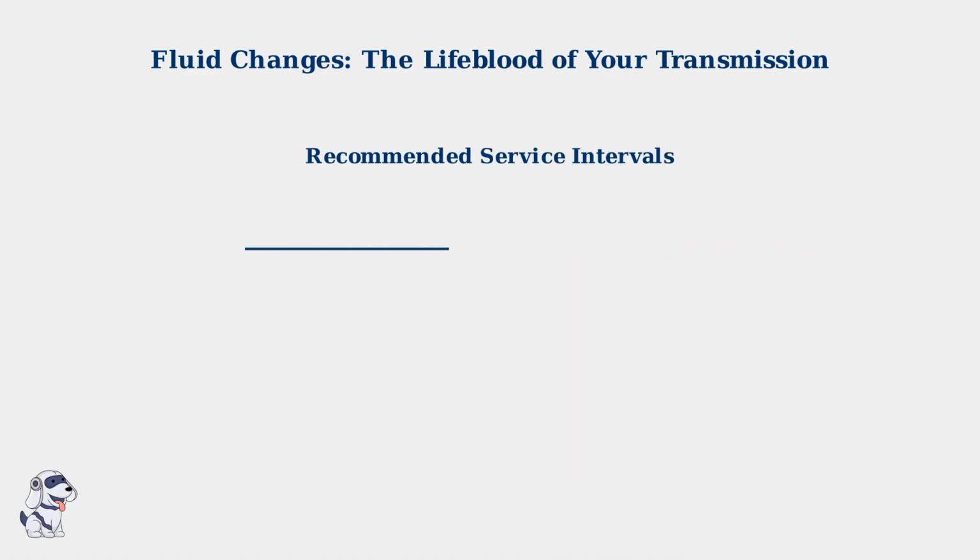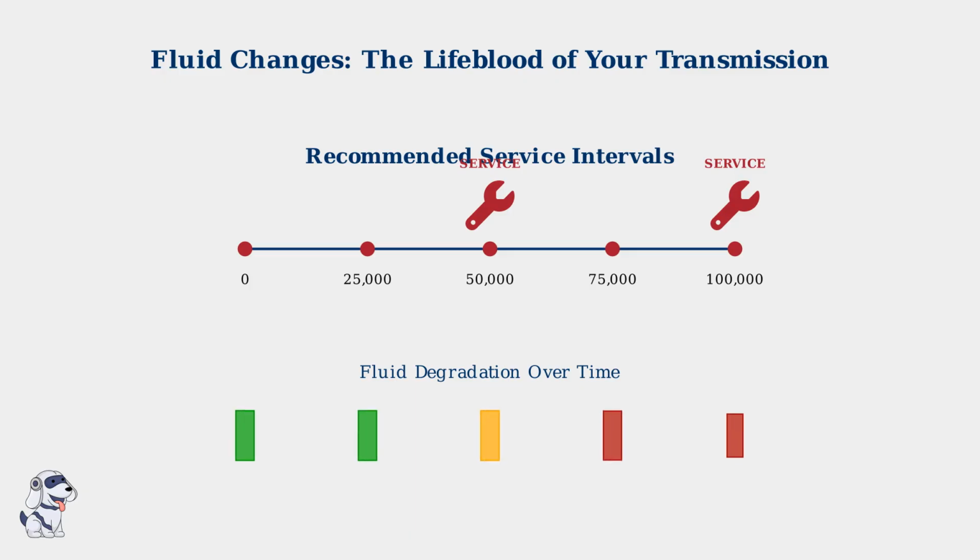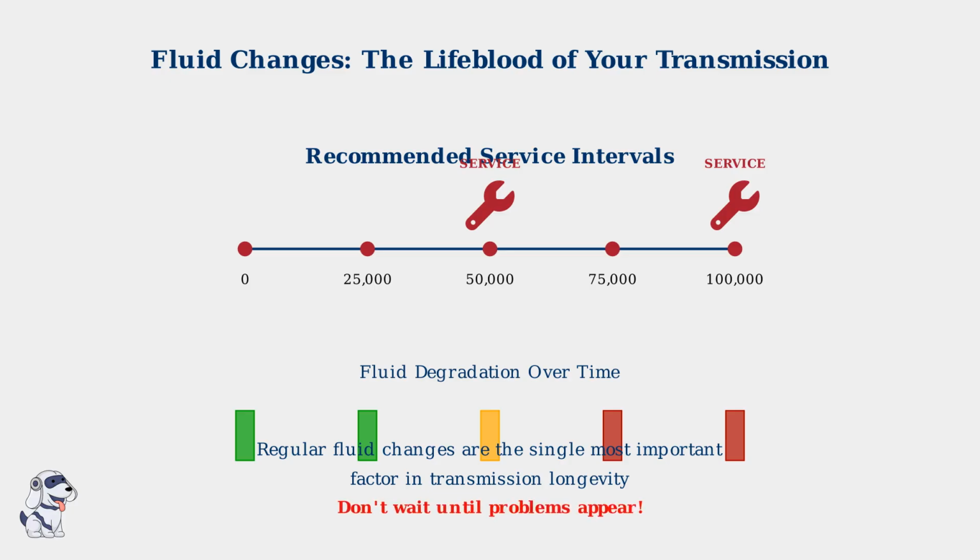For both the 8HP45 and 845RE transmissions, ZF recommends changing the fluid every 50,000 to 75,000 miles or every 8 years. This schedule prevents fluid degradation and maintains optimal performance throughout the transmission's life. Remember, regular fluid changes are the single most important factor in transmission longevity. Don't wait until problems appear. Preventive maintenance is always less expensive than repairs. Your transmission will reward you with years of reliable service when properly maintained.